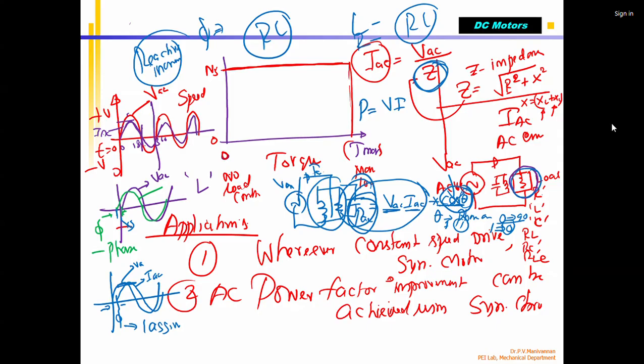So in big factories, you have a lot of tube lights, correct? For example, a plant may have hundreds of motors. Then lights, tube lights, which have chokes. Then you have fans to circulate air in the factory. That means a lot of inductive motors are connected. In that case, the power factor will become lesser and lesser. So to stop that, they put capacitor banks. Otherwise, they can put in synchronous motors.